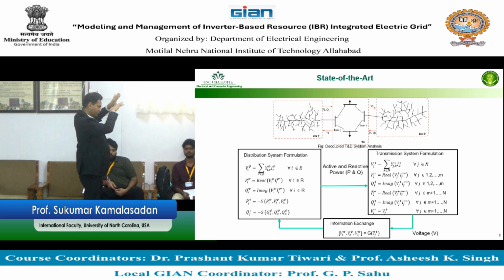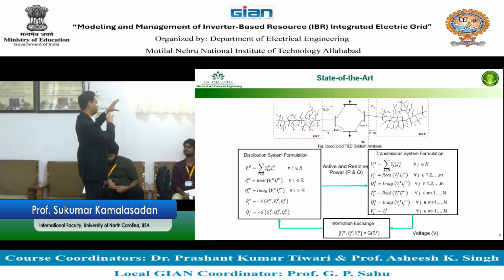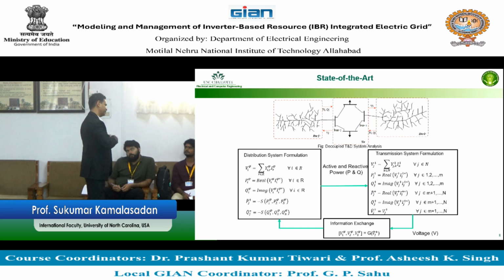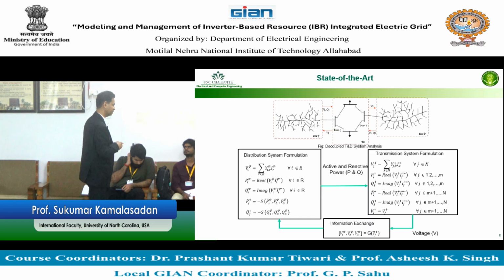You take the entire spot load and multiply it with a scaling number like 3 times, 2 times, because the load at each point in a network is not changing independently. It is only changing together, like a load variation. So if you change the spot load to a different number, it's a different operating condition. Now let's assume that in the iterative loop you keep changing this. Then it's chasing the goose. You will not be able to get the same operating condition all the time. So you cannot do that in the iterative loop, considering that the spot load is different all the time. That's why we need to reach that same load condition with the given distribution network.